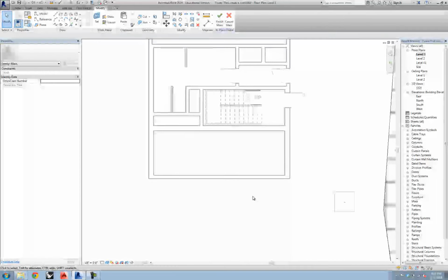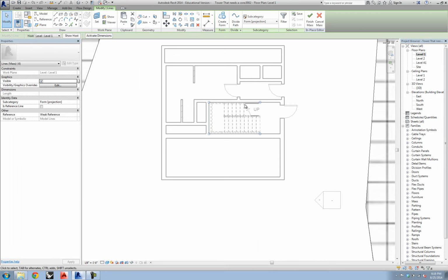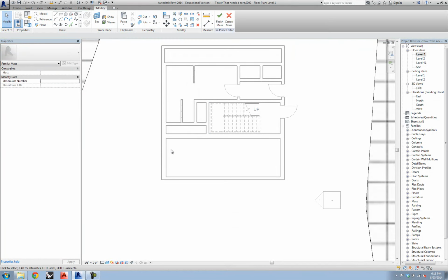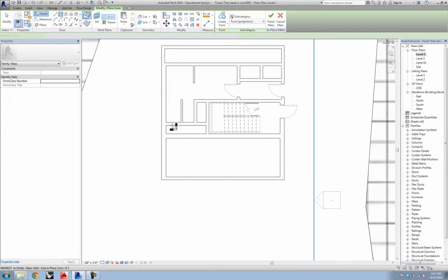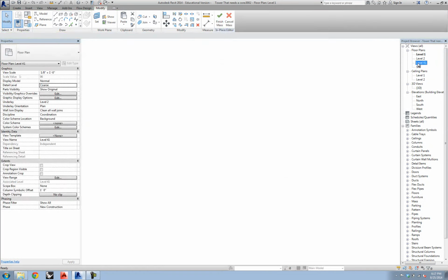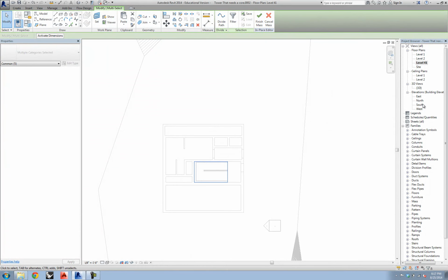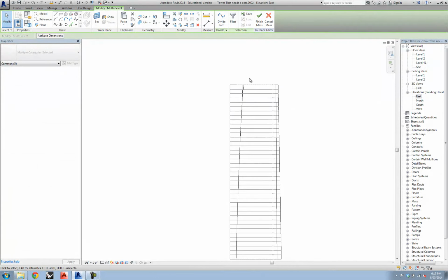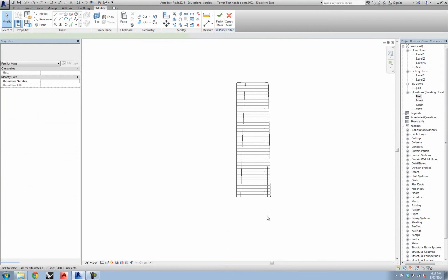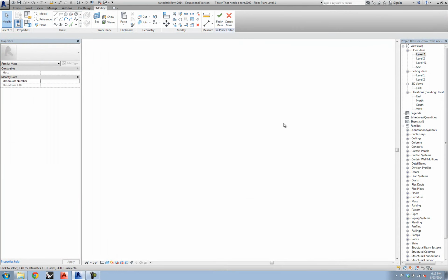Do these together. So, level 1, got our stair piece here. I'm going to use the same technique where I copy to clipboard. Actually, let's do them both at the same time. Well, maybe not. Okay. Do this. Copy to clip. Go to level 41. Paste, align to current view. Elevation. Draw a box to get them both selected. And hit void form. We'll go to level 1 again.